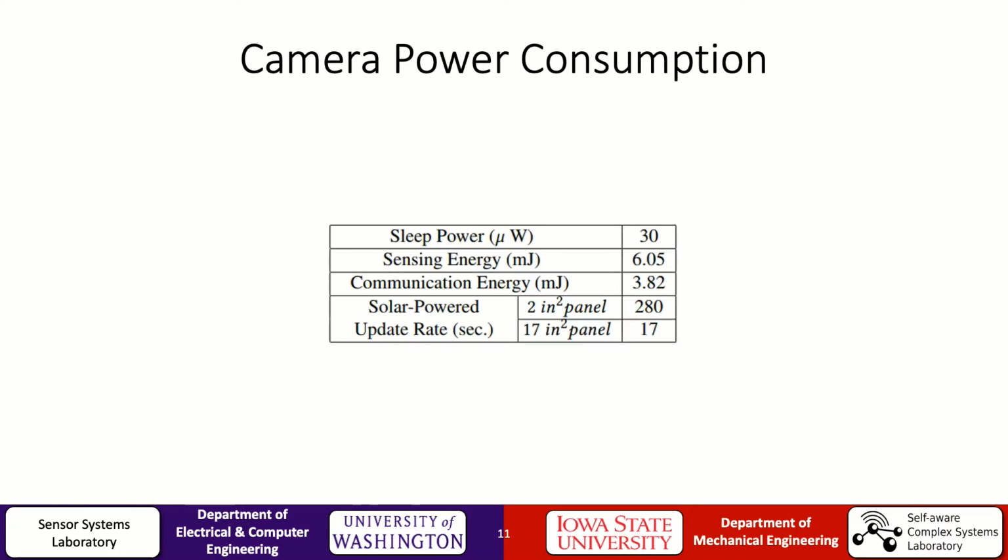Now we know how the battery-free cameras work. Let's measure the power consumption of the camera. We use a 2.2 ohm resistor in series with the camera and measure the voltage of the resistor. This voltage is 2.2 times the current that the camera and the resistor consume. We analyze the voltage data that the oscilloscope records and report the power numbers. Since the resistor value is small, we can assume that the camera consumes the total current.